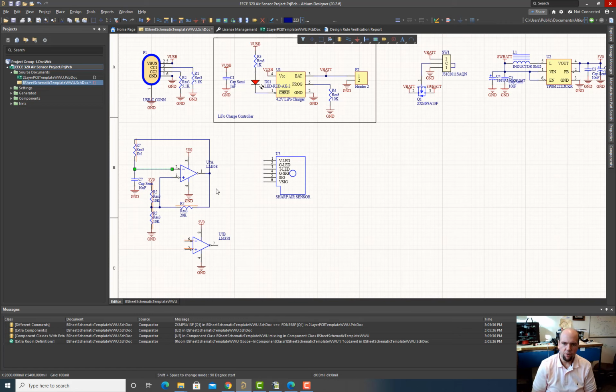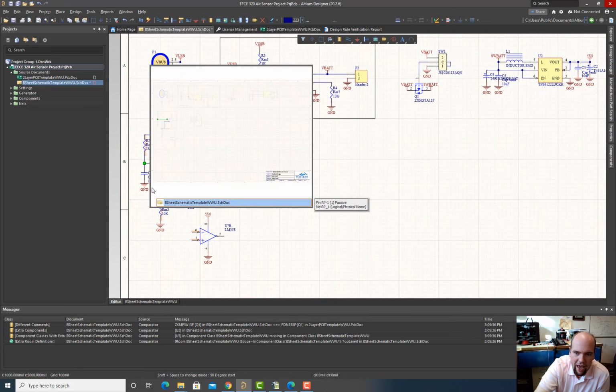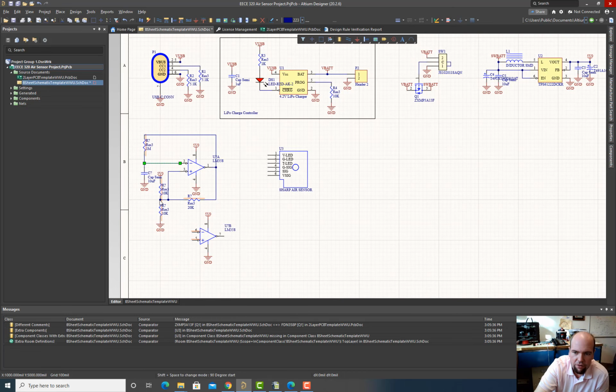But so this is an astable multivibrator. So the way this thing works, it's fairly straightforward if we just want to quickly talk about it. Assume this capacitor is discharged. Then what we have here is a little voltage divider. And this voltage divider is producing a voltage here of about half of 5 volts, so about 2.5 volts.